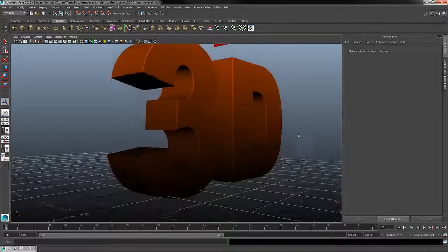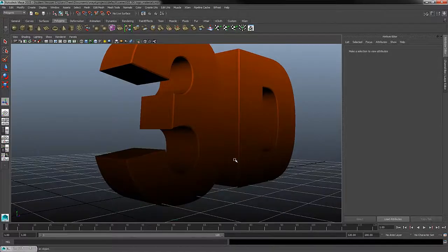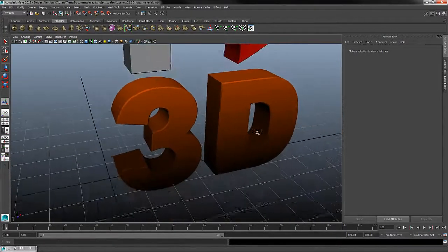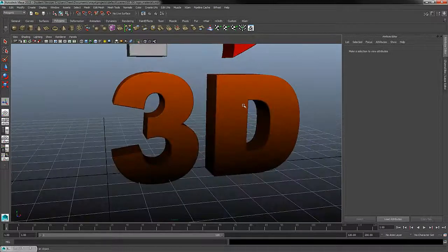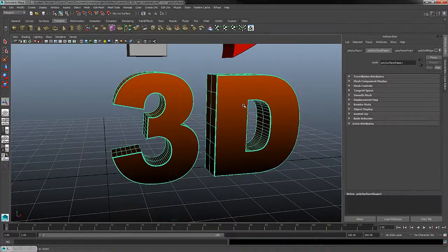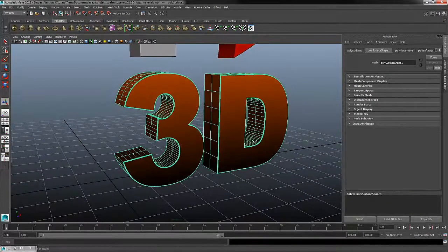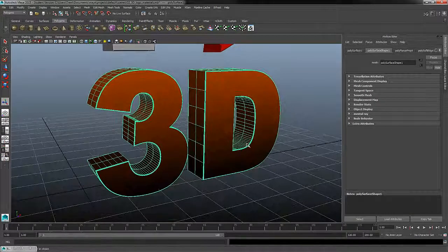Now you can see that my wallpaper texture, my ramp texture, is going from top to bottom. We go from a darker color up to a lighter, and it's not going from back to front anymore. So we properly mapped our 3D geometry. So again, that can be a complex topic, but just think of the illustration of applying wallpaper to your object, and that'll give you a good introduction of what UVs are all about.